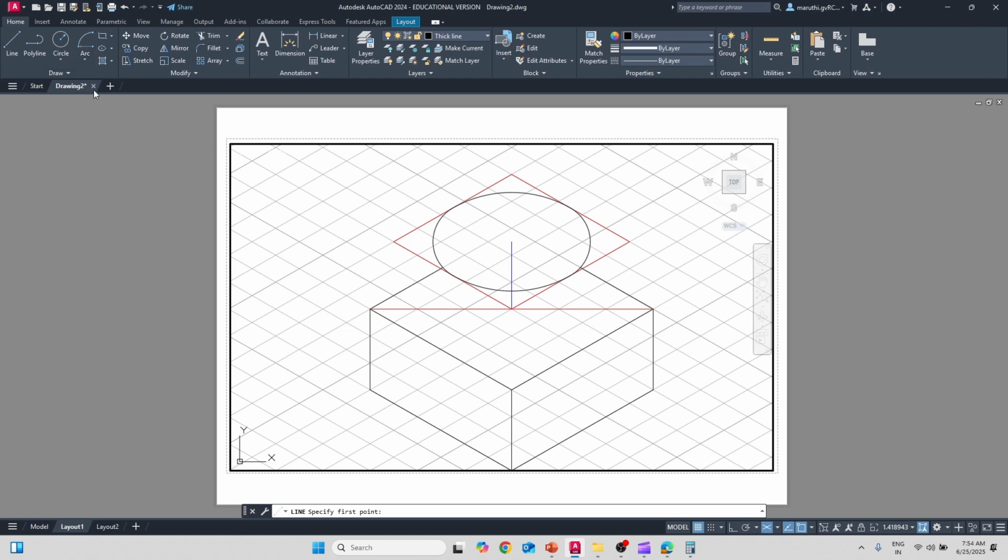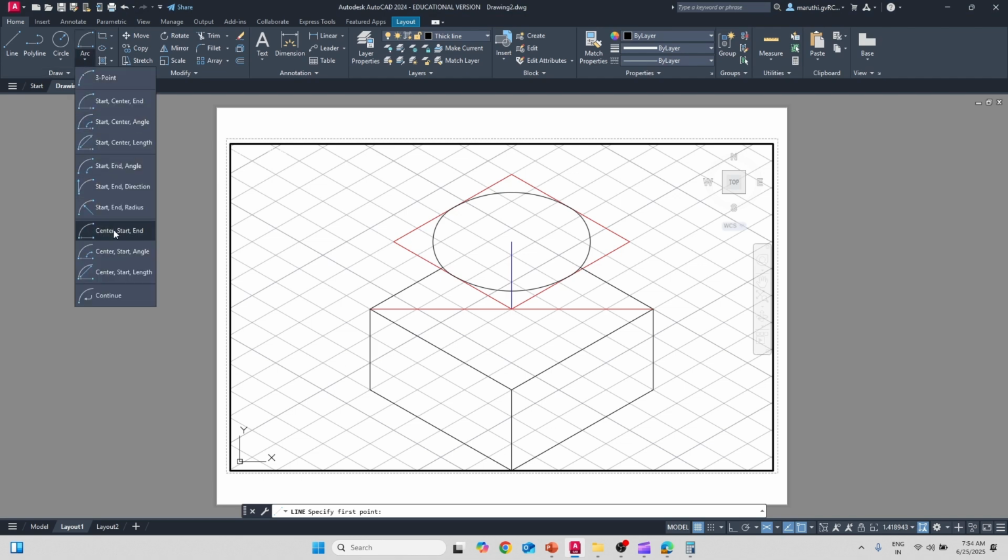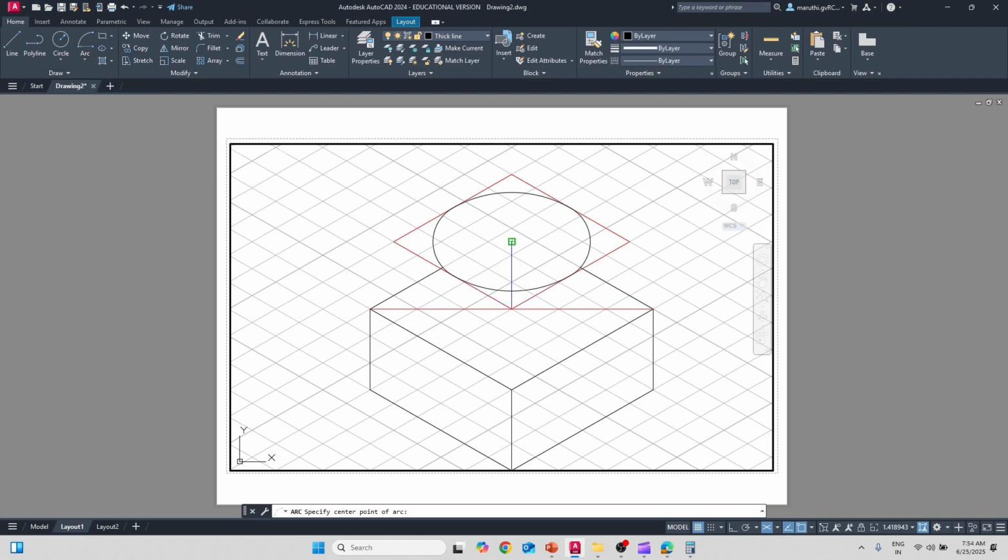Okay. Go for center, start from this center. Okay. 30.75, so we go for 30.75, enter. Now you draw the arc. But whatever arc you are going to draw now is not going to exactly touch this. What we need to do is this. If you want, you can draw this line up to here, rectangular. Then after that, you just connect it. Select line and just connect it.